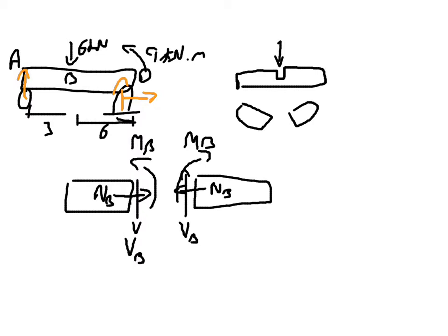Now, if we consider what's actually happening there, all of those effects on each side are equal in magnitude and opposite in direction. So when we put it back together, if we imagine it's one beam again, then there's no net result overall. So there are internal forces at work, but they're going to cancel out to give no net result. So what we'd do if we were trying to solve a problem is we'd take a cut along the place where we think it's going to be easy to analyse, draw free body diagrams for each side, label up the forces that are acting, and then see what equations of equilibrium we can apply. We'll do that now. We'll look at the example beginning on slide 10.